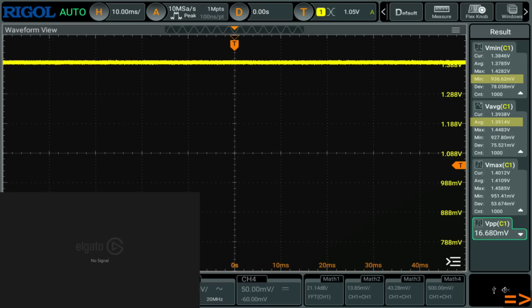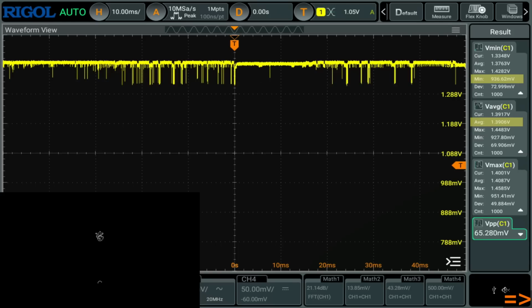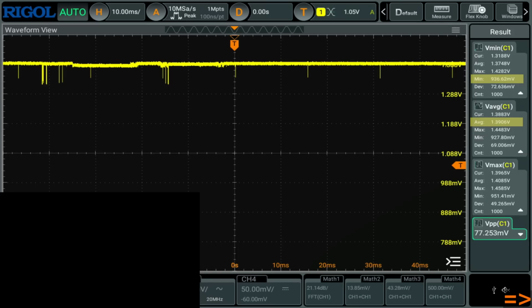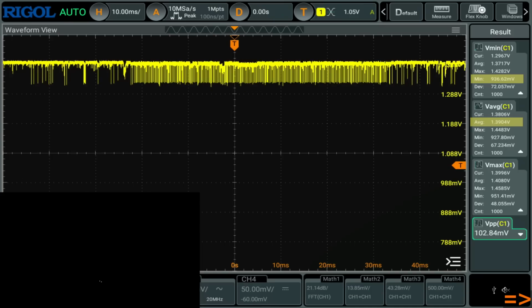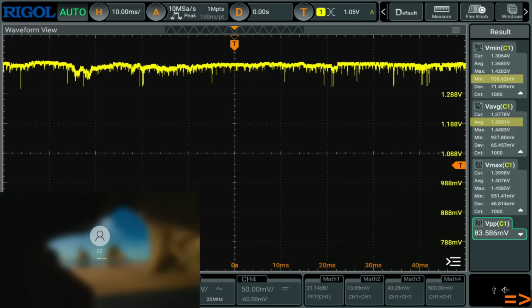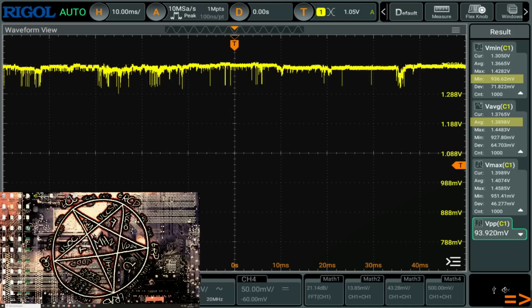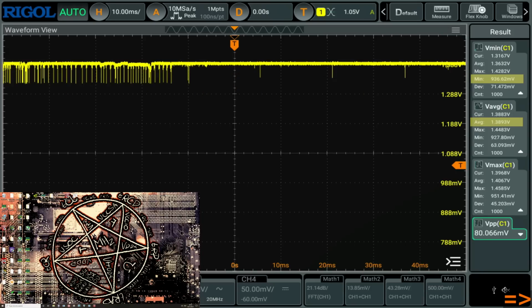And I guess the idea from MSI on this is that you can still use a very droopy LLC like level 8, but you're not going to have the insanely high idle voltage that you would potentially need. Yeah, so a decent idea. Obviously, if you put more time into tuning this, I think you could get better results.